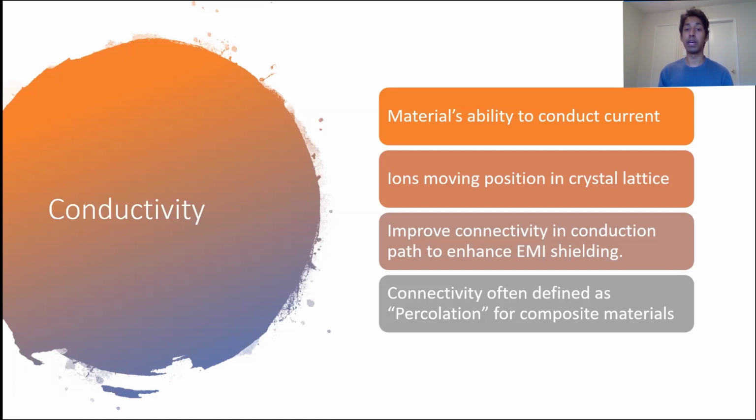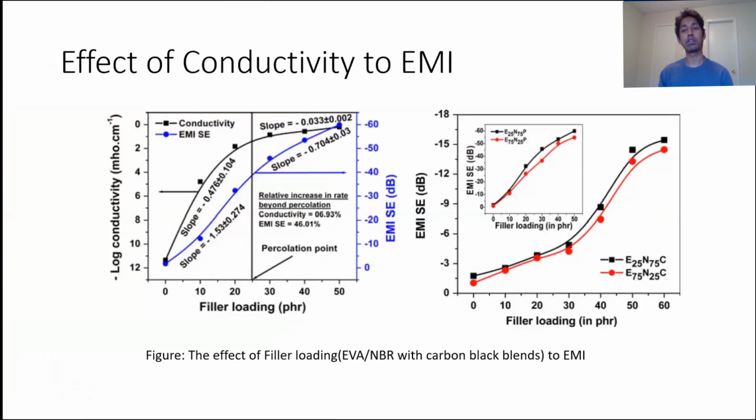Conductive filler can be carbon black, carbon nanotube, or various nanoparticles. If we consider any polymer composites, filler loading can increase the EMI shielding by enhancing conductivity or reducing the resistivity. Shielding can be manipulated by some other intrinsic or extrinsic parameters as well. The equation also provides some symbols for those. Shielding material thickness is an extrinsic parameter which can be used to control absorption or multiple-reflection dominated shielding.